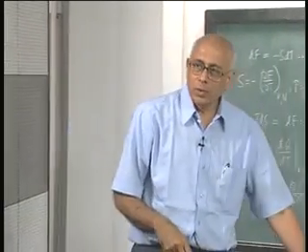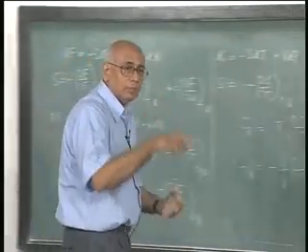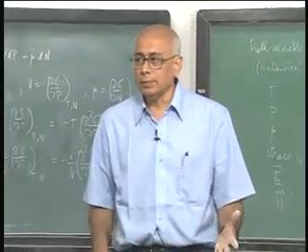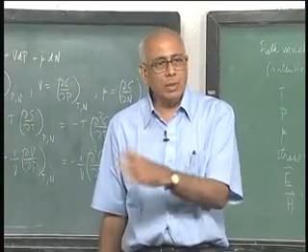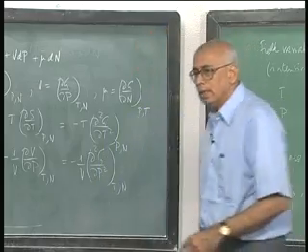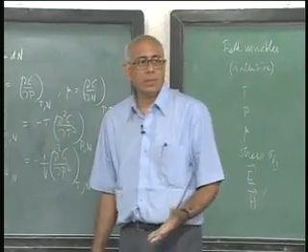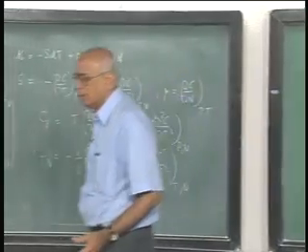And it's happening because it's a sort of network kind of object, it's a very crude model of it. So it's possible to have a Poisson ratio that's negative, but it can't be more negative than -1. So it runs from -1 to +1/2, and what is it for most materials, most metals, normal stuff? About 0.25, 0.3, something like that, right.